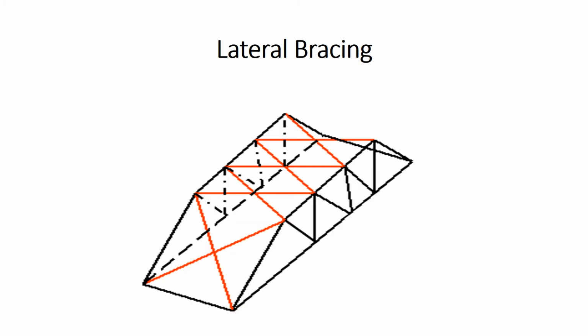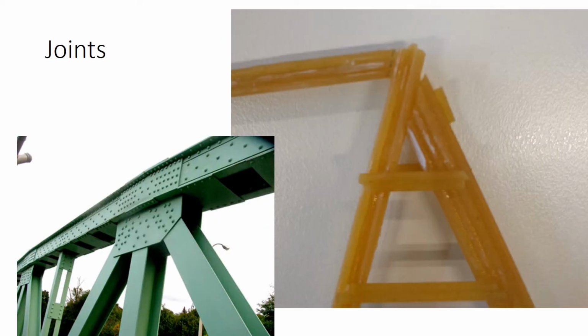Lateral bracing was used for keeping the 2 sides of the bridge together and also preventing twisting. Only bracing was required for the top and side members. This is because they were all compression members and will deform much more than the tension members on the base. Besides joining the 2 sides, the lateral bracing strengthens the bridge significantly, as it also shortens the compression members. This is because halving the length of a spaghetti compression member increases its strength by a factor of 4.